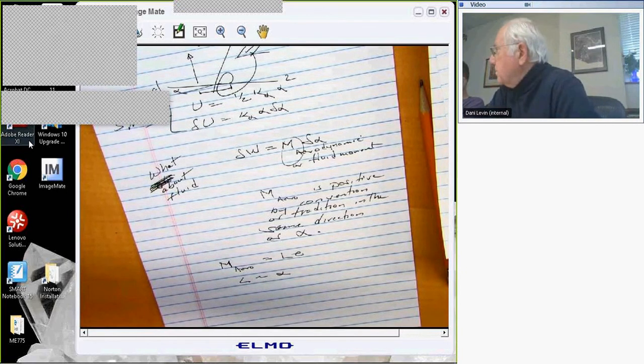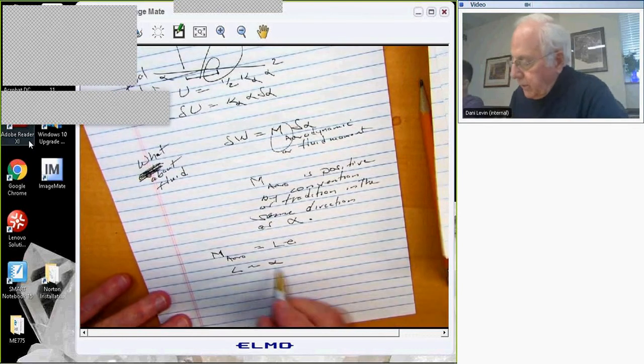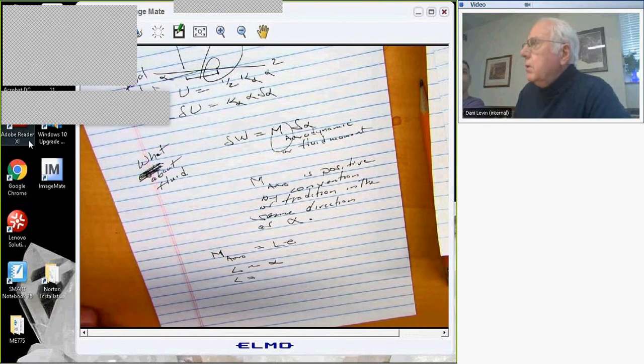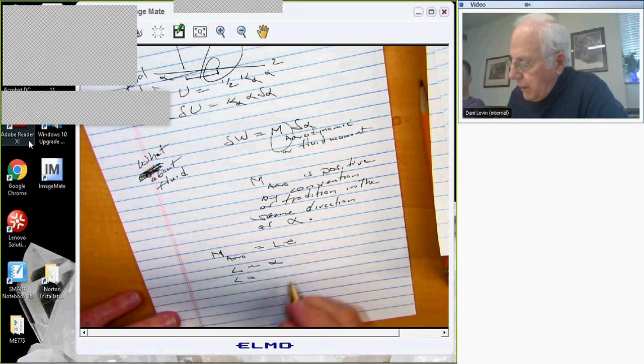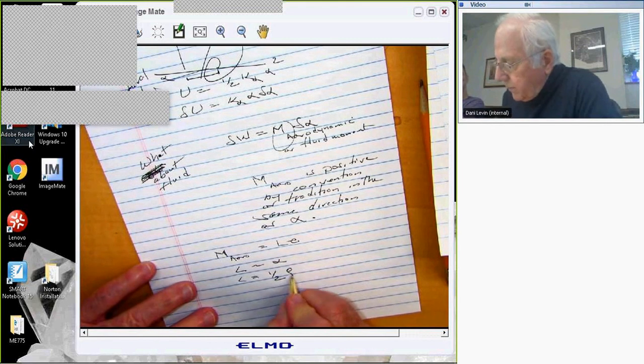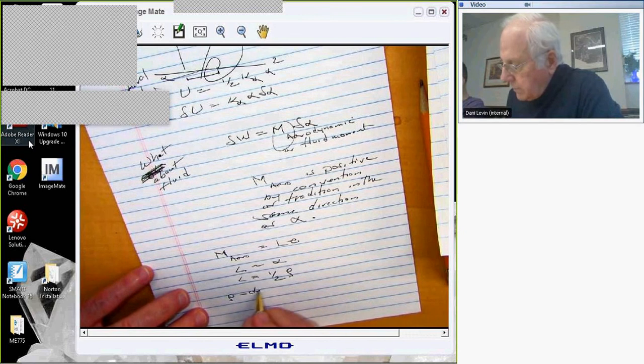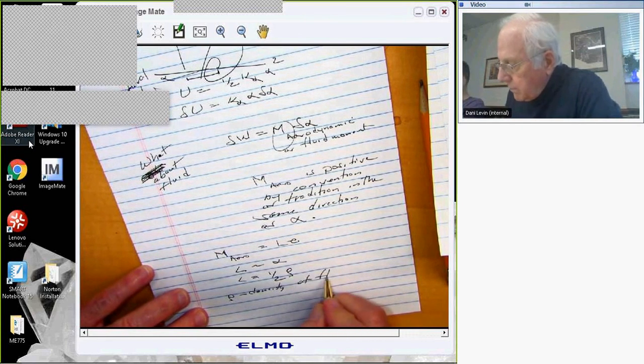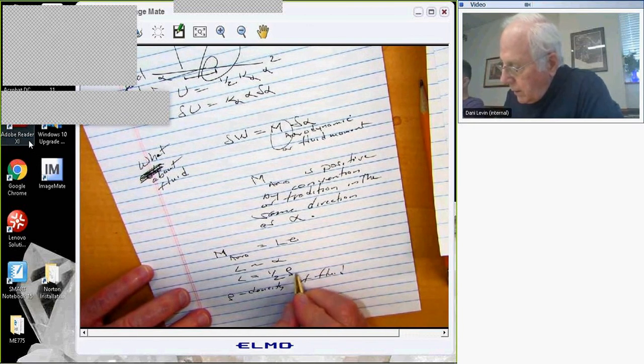In fact, the reason airplanes fly is because there is some lift as a result of an alpha. If that didn't happen, we'd still be on the ground, right? And there's a coefficient which comes from aerodynamic theory, and that theory could be something as basic as dimensional analysis, or it could come from solving some equations of fluid motion, but it looks like the following. It's 1/2. There are 1/2s in aerodynamic theory, just as there are in structural analysis, times the density of the fluid, times u squared.